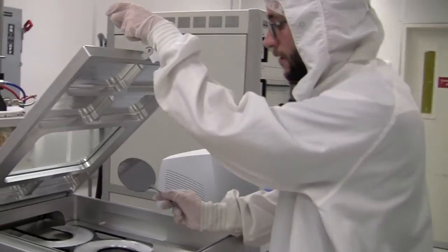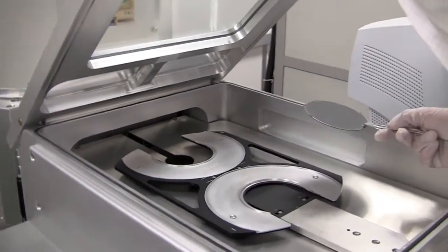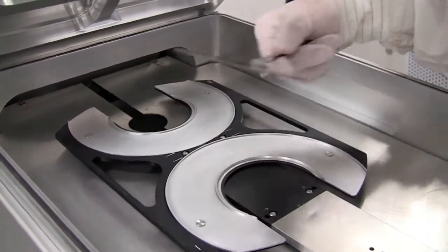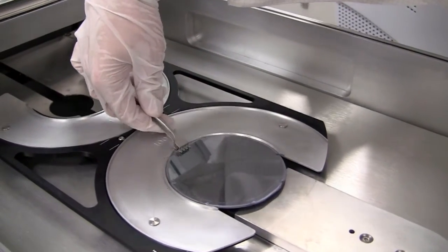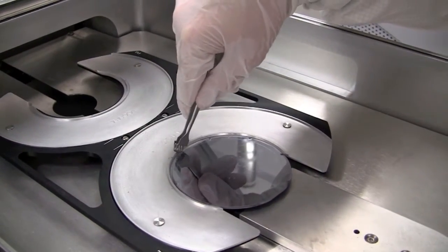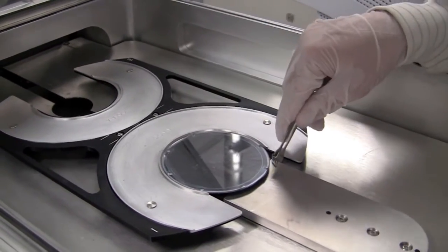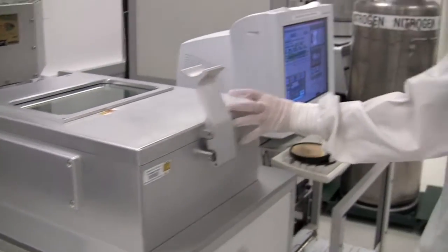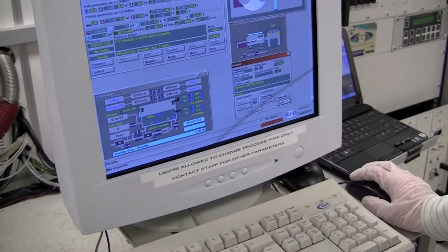As you will see, the wafers usually have a flat, and on the loading carousel we have a small line. Please align the flat with the line on the desired spot. Once we have the wafer properly loaded, we close the load lock chamber, go to the transfer window, and press Pump and Map.